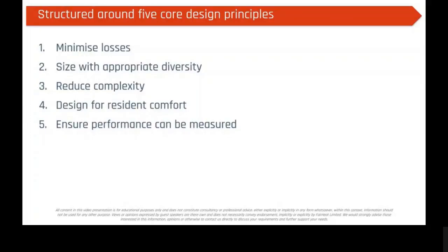And we want our plant to be operating at its design condition, or as close to it as possible. If I stretch that and put in a megawatt boiler when I actually only need 100 kilowatts, it's not going to operate. Also, if we size our pump too big, we get a high surface area and we lose a lot of heat off those. So it goes back to minimizing losses. So getting the system sized correctly is absolutely critical.